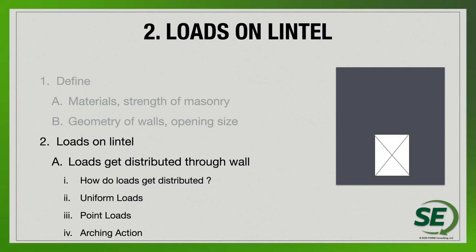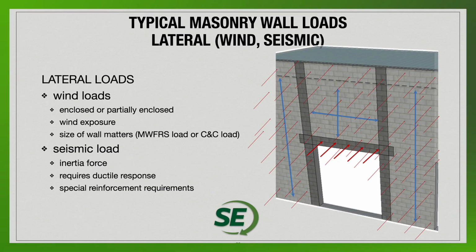spot. So making sure that we understand not just the lateral loads here. You can see the lateral forces that we maybe want to look at for the lintel elements. We do have a lot of exterior walls with masonry lintels, so certainly making sure that we have the horizontal bending capacity that we can consider. And then all the other elements that are sized and framed around it and what the different forces are certainly going to affect what loads need to be transferred then to that lintel as well.